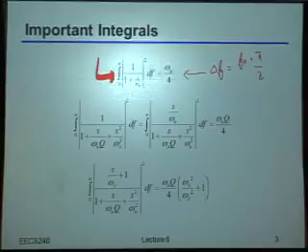The way I got to that was, of course, just that omega naught is 2 pi times f naught. So notice, interestingly enough, the effective bandwidth is actually wider than the low-pass filter cutoff frequency, or the 3 dB point of the low-pass filter.